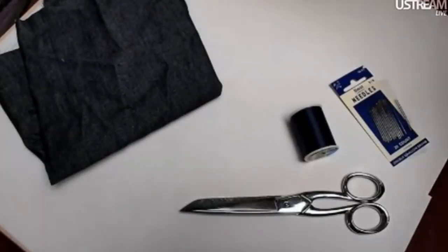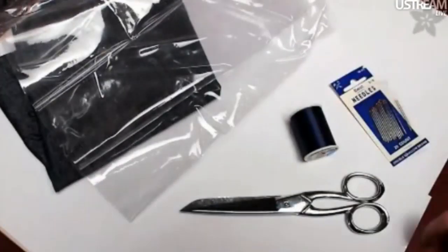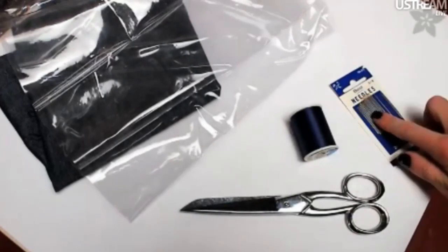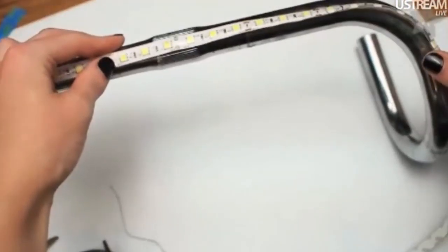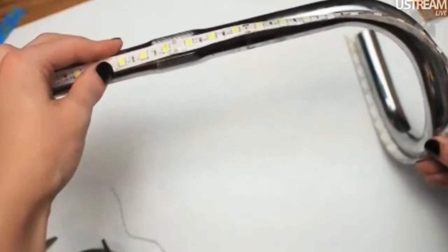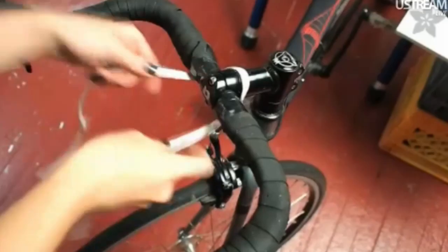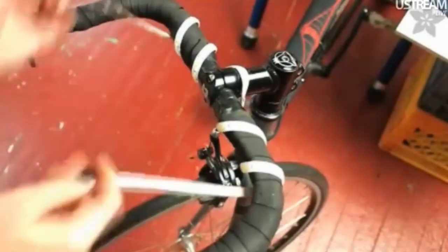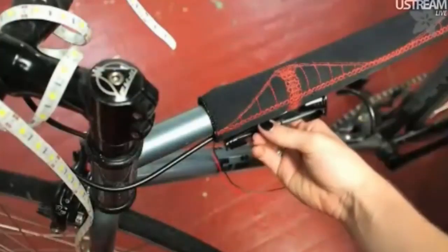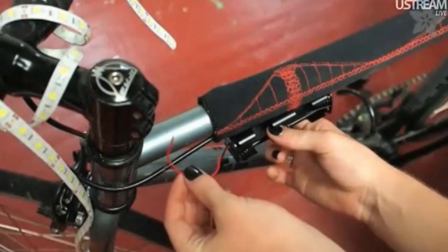To make the battery bag, you'll need some fabric, some tablecloth vinyl, as well as scissors, thread, and needles, which you can pick up in the Adafruit store. Start by laying out your LED tape on your handlebars. 1 meter will cover a strip along these drop bars, while I'll use 2 meters on my own bike to do a spiral design. We'll store the batteries right underneath the top tube with a wire leading up to the